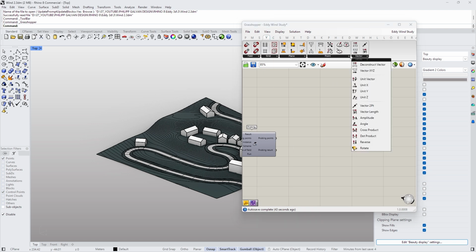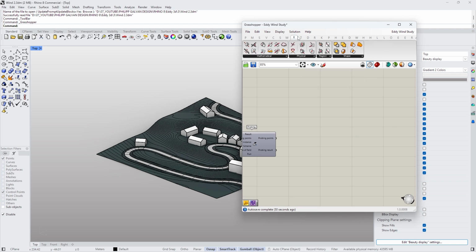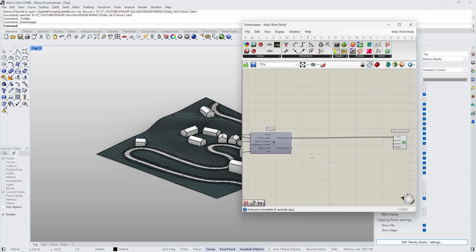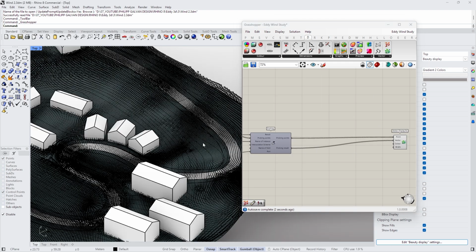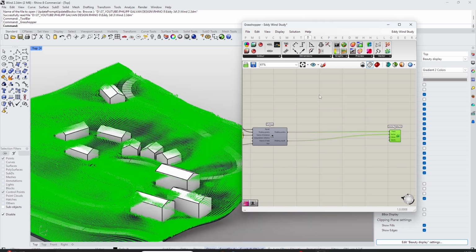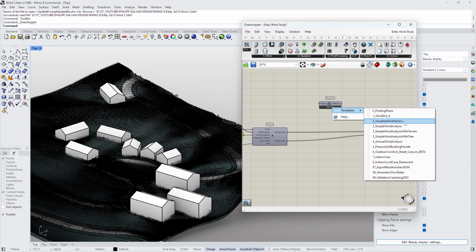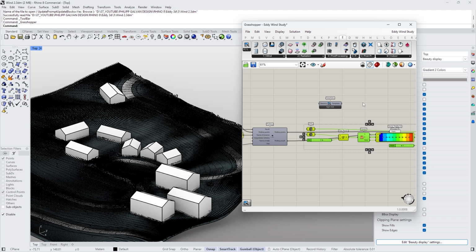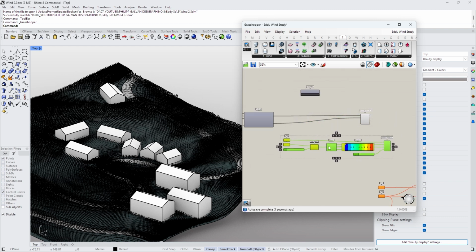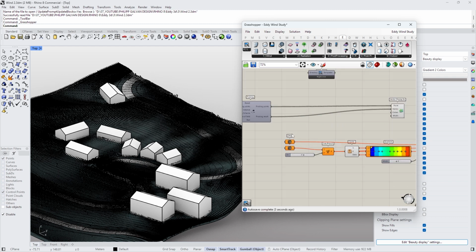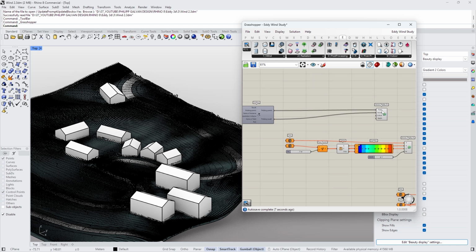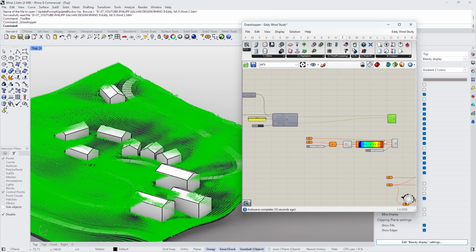Okay, so first of all, there is a tool in Grasshopper. It's called vector display, and you should see the vectors here in black. Now the best way to move forward from this point is to cheat a bit. So I get the templates again, and go in here and say I want to visualize the wind vectors. That gives me the whole setup I need in order to visualize the vectors. And I can delete this, and you see you have the same tool.